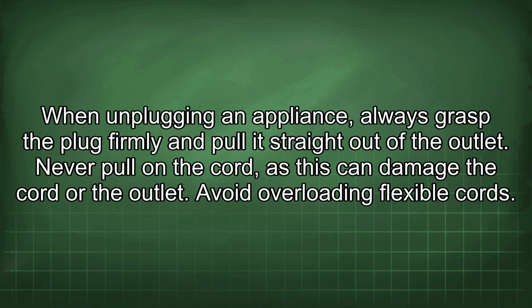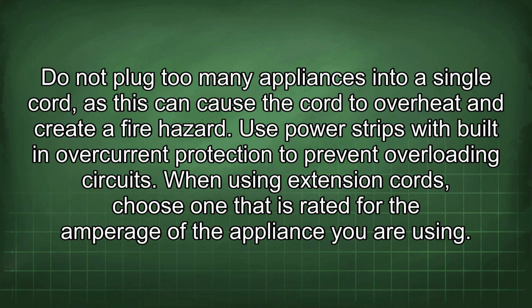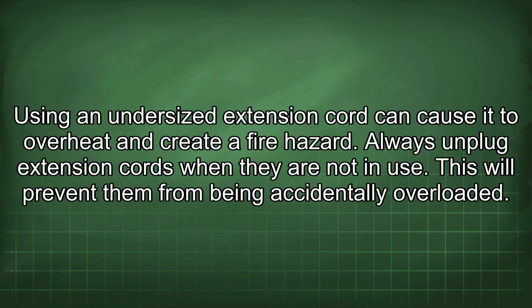Avoid overloading flexible cords. Do not plug too many appliances into a single cord, as this can cause the cord to overheat and create a fire hazard. Use power strips with built-in overcurrent protection to prevent overloading circuits. When using extension cords, choose one that is rated for the amperage of the appliance you are using. Using an undersized extension cord can cause it to overheat and create a fire hazard. Always unplug extension cords when they are not in use. This will prevent them from being accidentally overloaded.